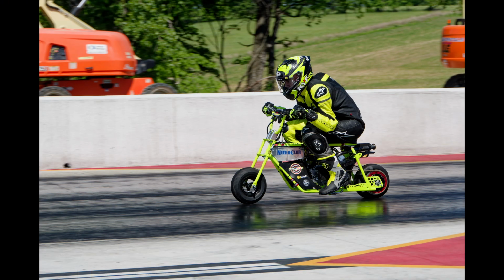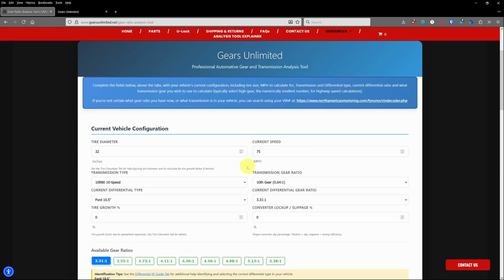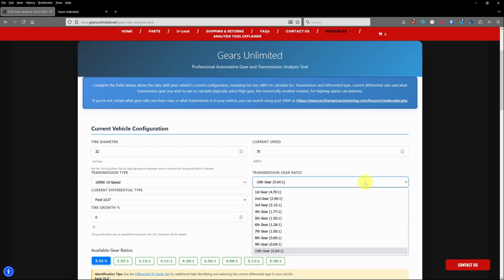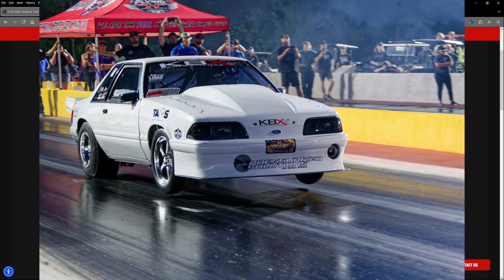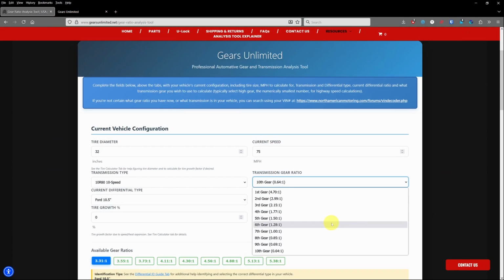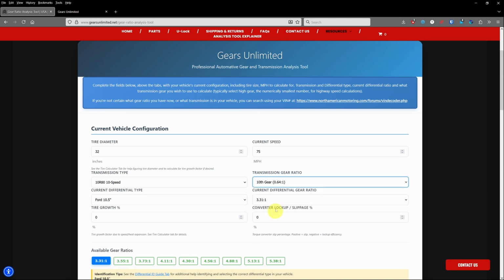Well, almost anything. You'll also need to specify which transmission gear you want to base the calculations on. Choose the highest gear available for a street or highway application, or a gear you normally find yourself in when hauling a load, or any gear that's appropriate for your situation. A typical example that might be out of the ordinary: an 8th mile drag racer might not make it into high gear at the finish line. Here, select the gear you're in or expect to be in at your finish line miles per hour as you cross the stripe.